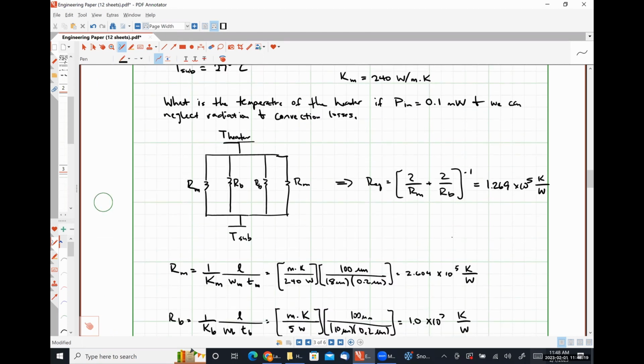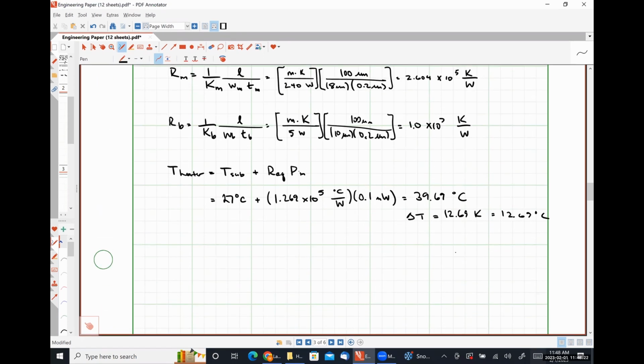All right, so wrapping things up for today. Thermal resistance is related to the speed at which temperature changes can occur as well, right? So if we have a MEMS device, it's usually important to us how quickly we can heat or cool that device, because that tells us how quickly we can cause a displacement, right? So this is outside of the scope of the example problem, so I'm just going to put a line there.